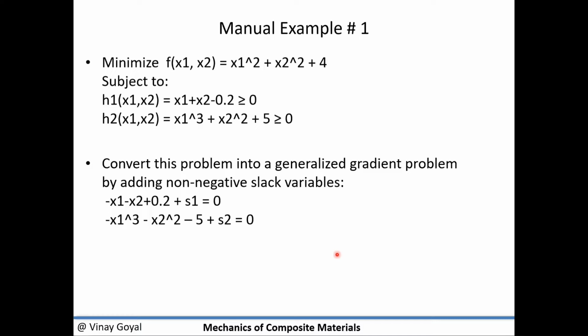So if I want to minimize this function f, which has two design variables, x1 and x2, and the function was x1 squared plus x2 squared plus 4, minimization of this function relative to these variables can be visually looked at here. If x was a negative value, f can only go up because a negative value squared only adds to 4. If x was positive, you're still going to increase the value of 4 to a higher number. So I'm not really minimizing. My only solution is really x1 equals 0, x2 equals 0, but it violates a constraint.